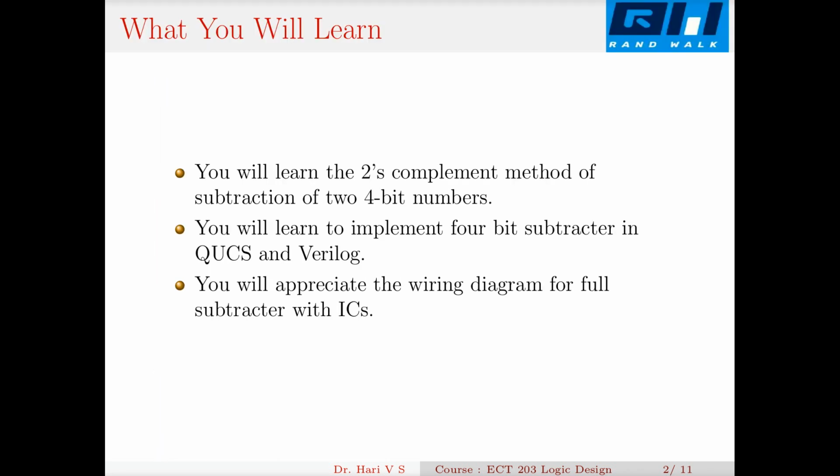What you will learn in this video is the 2's complement method of subtraction of two 4-bit numbers. Then you will learn to implement the 4-bit subtractor in QUCS and Verilog. Then you will appreciate the wiring diagram for the 4-bit subtractor with the integrated circuit 4-bit adder.